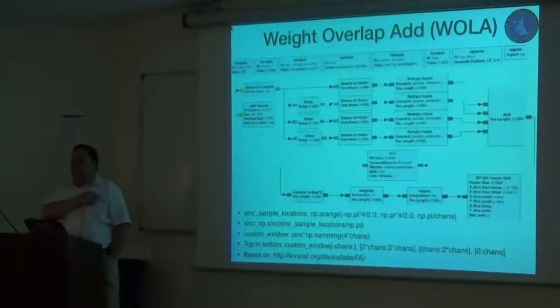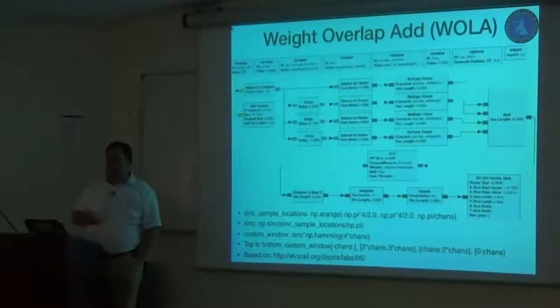You use a specific block to flush the pipeline. Yeah. And how does it compare to reducing the buffer size? I've tried that. I've tried reducing the buffer size, and my conclusion from that was that GNU Radio was simply ignoring me. So, I mean, each block I think has like an output or an input buffer size. And of course, before I was using the repeat block, I actually tried doing that. But that does not actually change the update rate at all. And if there's people really familiar with the internals of GNU Radio, they can probably tell me why. And then I will take away this hack and do this properly. But at the moment, this solution works.